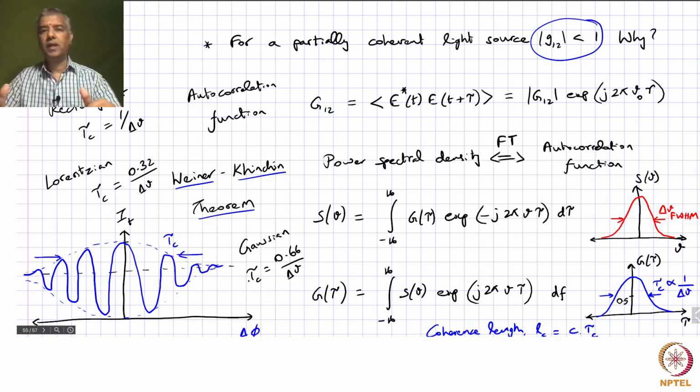A similar example we were mentioning is when we want to pick up information from long distances, say tens of kilometers. We said you could use what is called a phase OTDR. Previously we looked at OTDR from the perspective of picking up Rayleigh scattering, primarily interested in the amplitude or the intensity of the Rayleigh scattered light. But now you can look at the phase of the Rayleigh scattered light, and you can possibly detect perturbations happening several kilometers away.